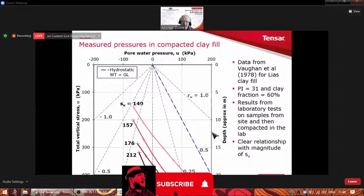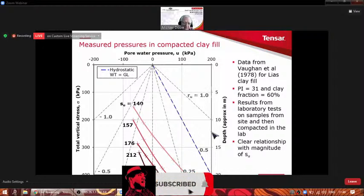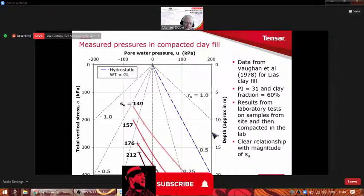Same diagram, I don't need to explain that again, but in this case, those 4 lines are all derived from doing laboratory testing on a UK clay called the Lias clay, which is a reasonably plastic clay. A number of samples have been recompacted to achieve a certain undrained shear strength in the laboratory, and then a test is done to look at the relationship between the vertical stress and the pore pressure. And you see the nature of that curve.